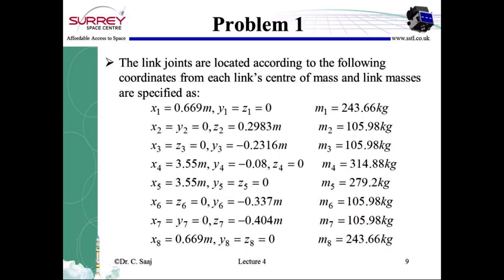And using the inertia matrix, which is based on the principal moments of inertia, you are asked to work out the new moment of inertia with respect to the joint coordinate system. And you can find this using the parallel axis theorem that we just discussed.